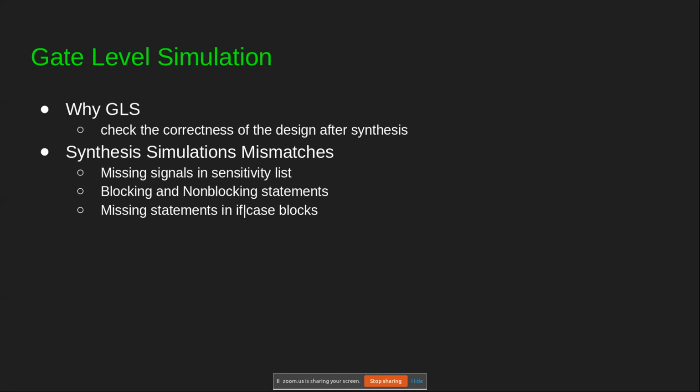the synthesis tool generating logic that is not intended. Some of the common cases are missing signals in the sensitivity list, using blocking and non-blocking statements where they are not supposed to be, and a missing statement in case blocks, which is a frequent reason for inference of latches.